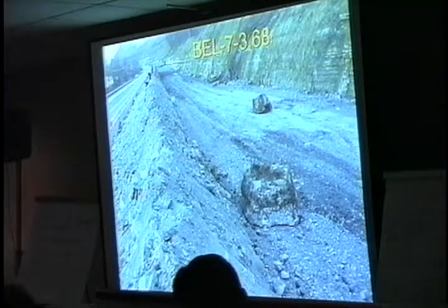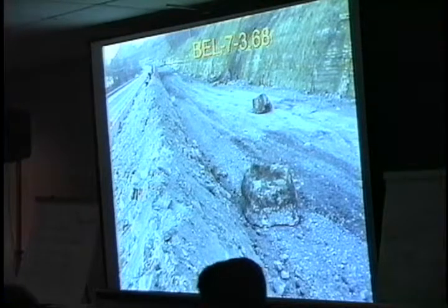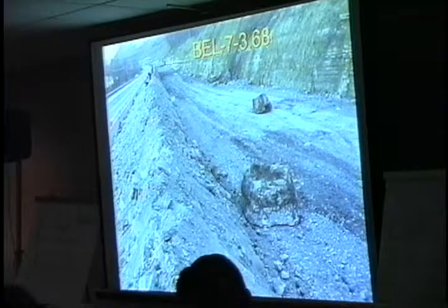Three things were considered. First, trying to restrain, as we talked about previously, the soil mass that was failing, and with some thought there, I think it was decided that we're looking at 12-foot diameter side-by-side caissons with substantial reinforcement that are going, who knows, 50 or 60 feet deep, even deeper, socketed into rock, or we're building a rock berm somewhere in the river, and I don't think the Corps would be too happy with us putting 30 feet of stone in the river halfway out. So restraint was considered not really practical in this case.